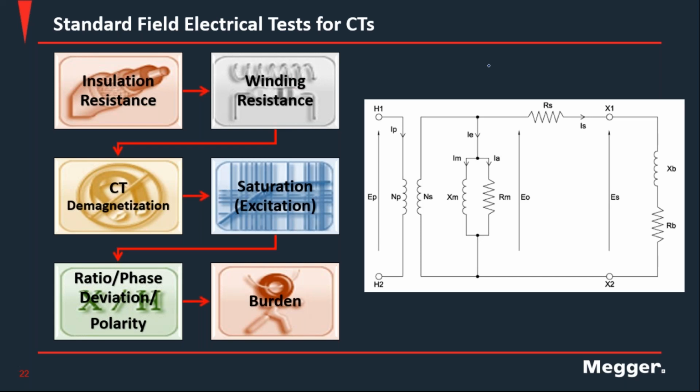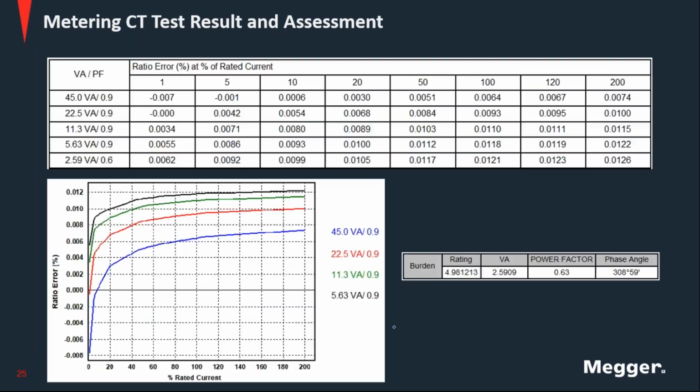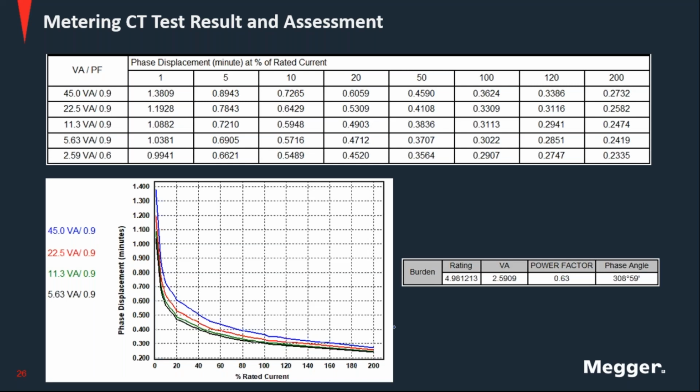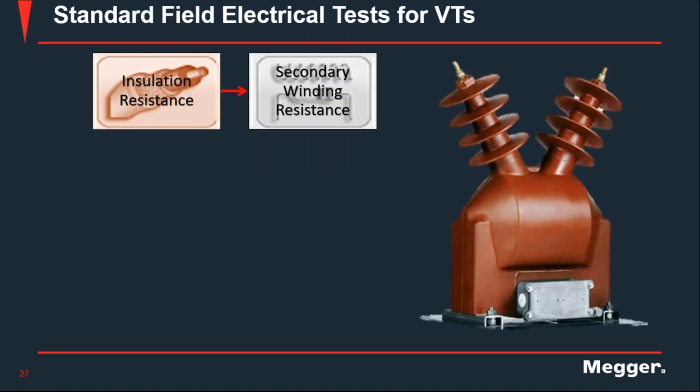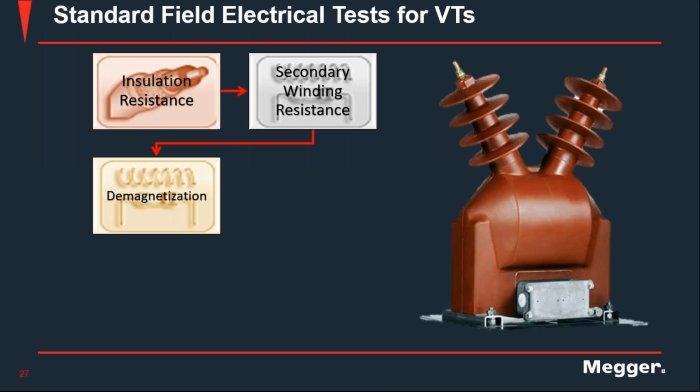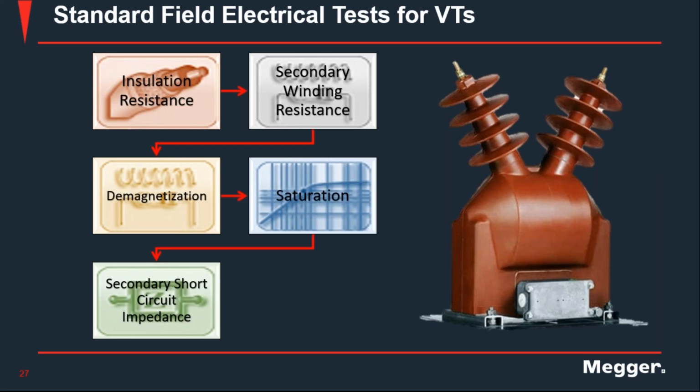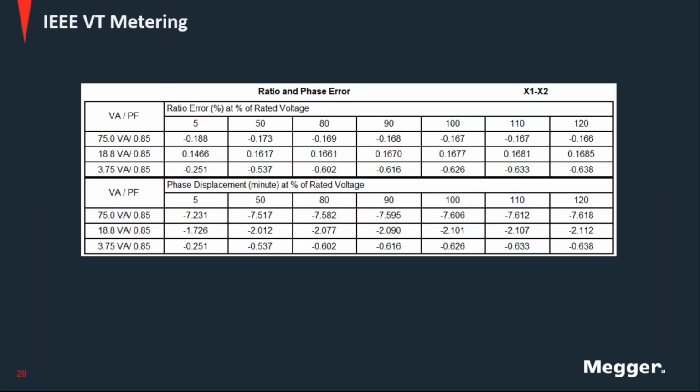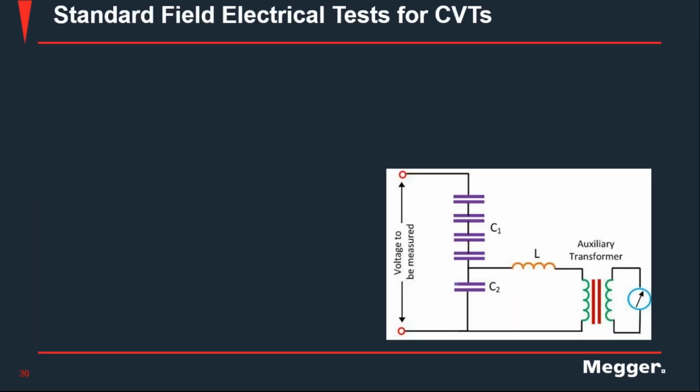Well, the short answer is that for the purposes of this presentation, yes, they are. For the purposes of doing the measurements, and what they are used for in the system from protection and measurement perspectives, yes, they are. However, there's a slight difference in that a CCVT is typically a CVT which is also used to couple with power line carrier communications in power systems. But the terms are typically used interchangeably.